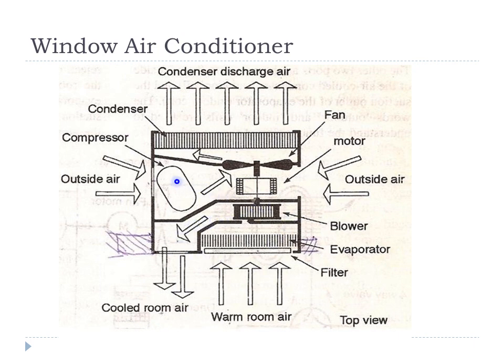And we have another outer compartment where you can see a compressor, a fan, and a motor. This motor is rotating this fan, and from here outside air can come into this compartment. So when we start an AC, what will happen? The compressor starts working, and the high temperature refrigerant will enter the condenser coil.